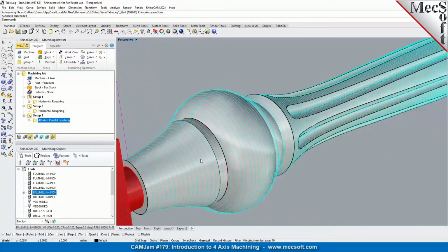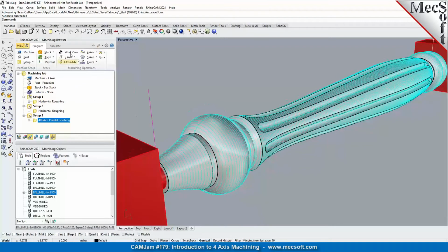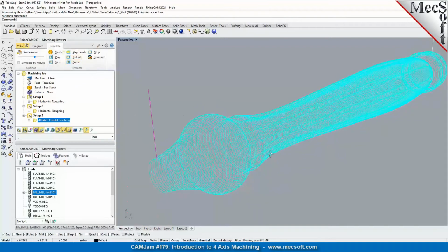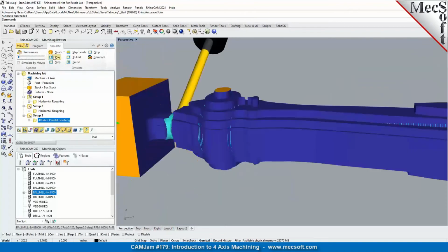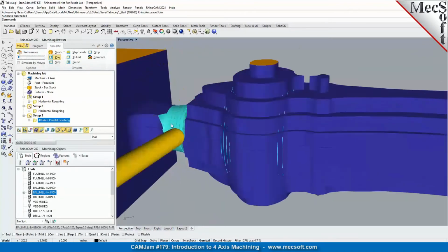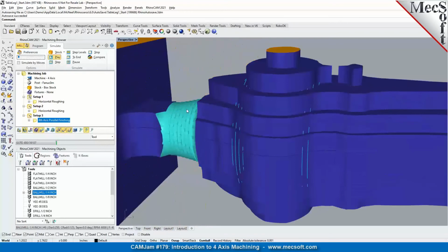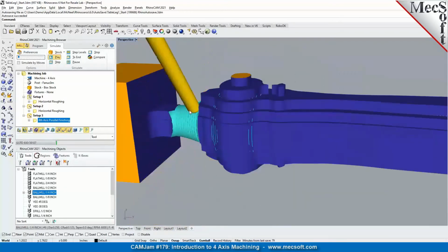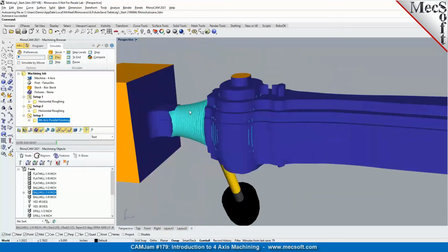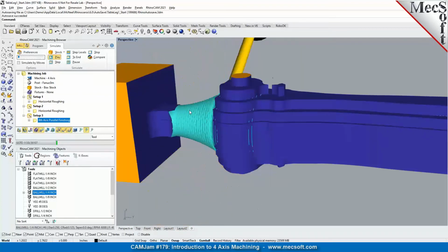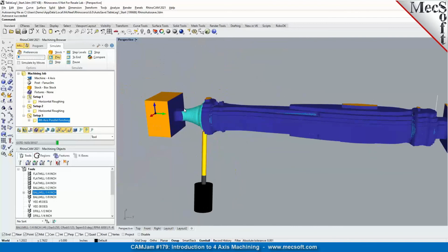All right, so that's the across axis. And as we run the simulation here, you will notice that you're making complete 360 rotations for each cut. As you step over, you're going from 0 to 360, 360 back to 0. Since I've set it to zigzag, if you choose zig, it basically goes from 0, 360, 360, 720. So it basically keeps incrementing. So in this case, we are cutting back and forth in a cross pattern.